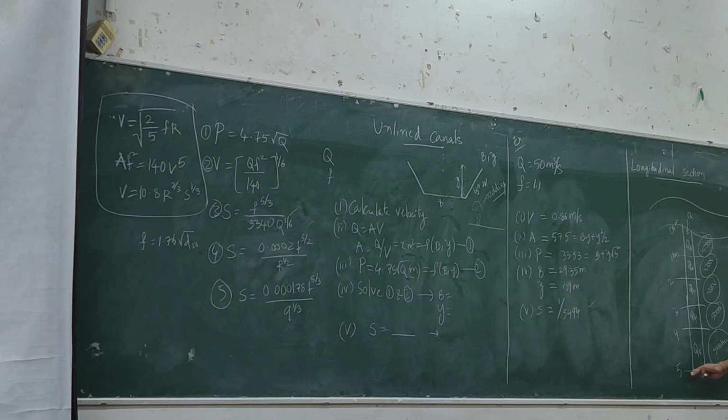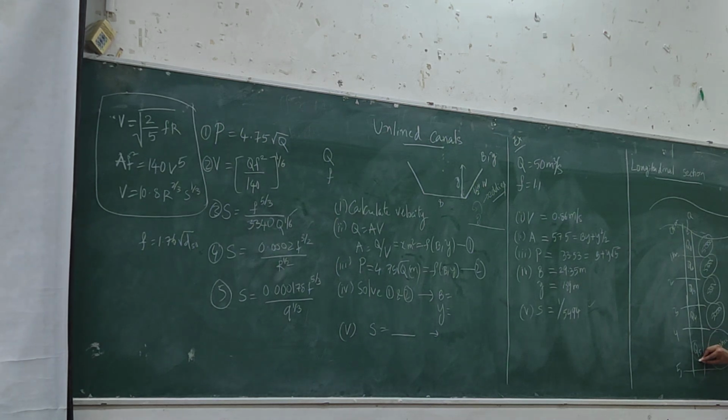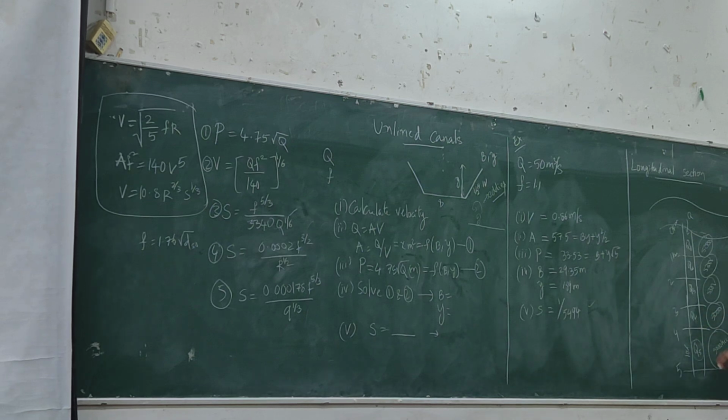And you usually start from the end. So let's say here I have a discharge Q5, and we consider that there are 10% of losses because of conveyance from 4 to 5 kilometers. Now here, if you want to design this section, you would consider Q5 plus the losses.